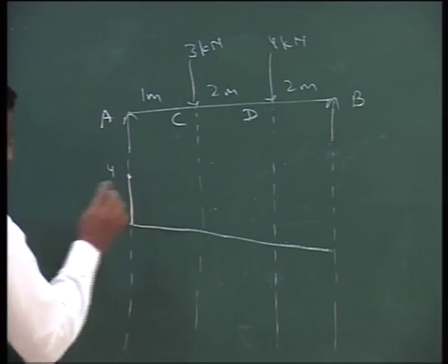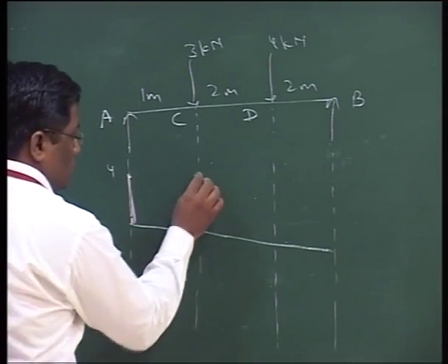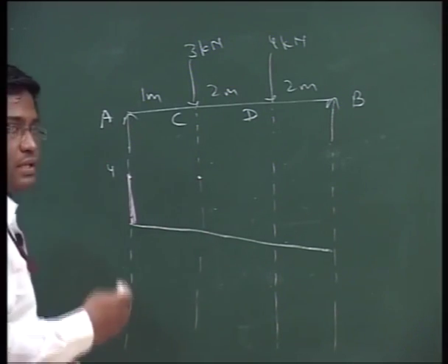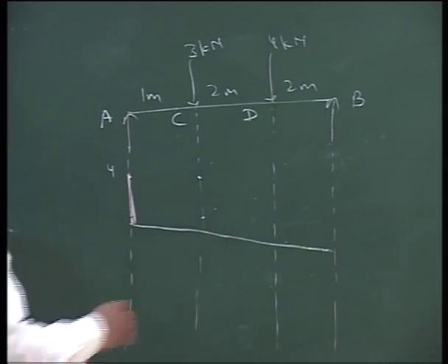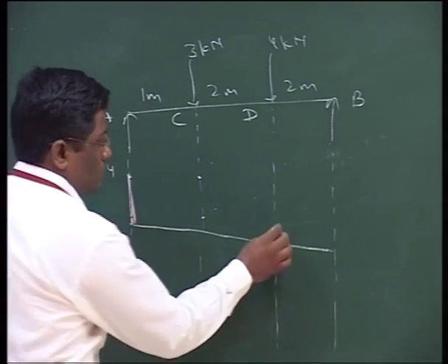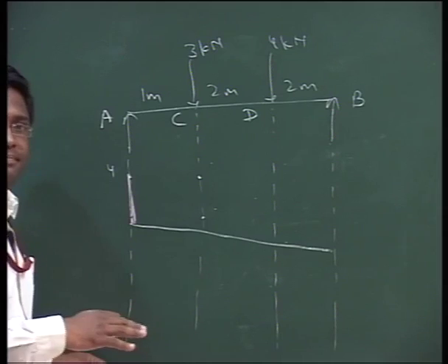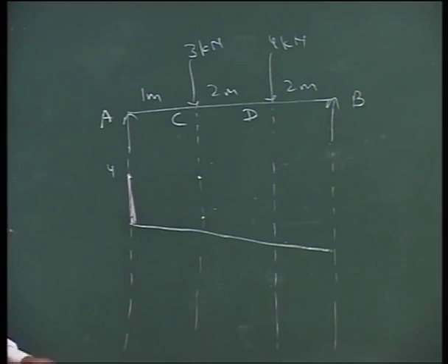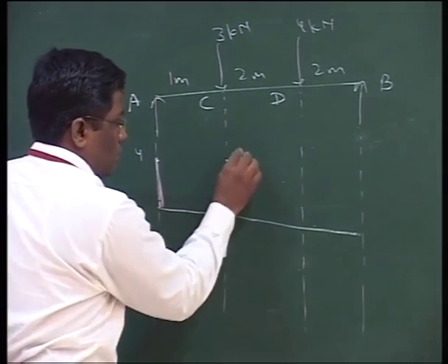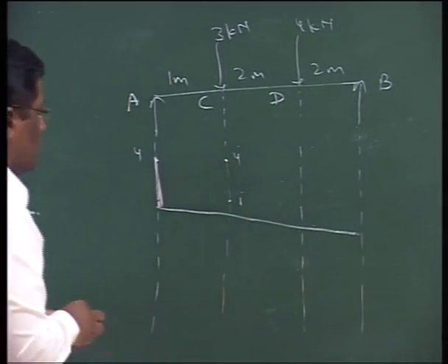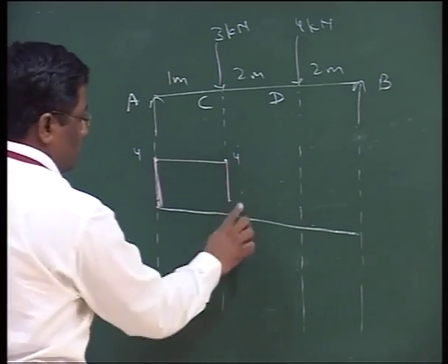We can now FC left is also plus 4. FC right, that means the right side of C is plus 1. So we are still on C. Now FC left was plus 4, FC right was 1. So now we can draw or stretch this line here.